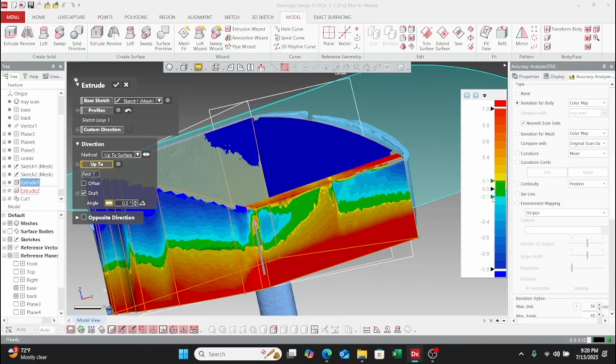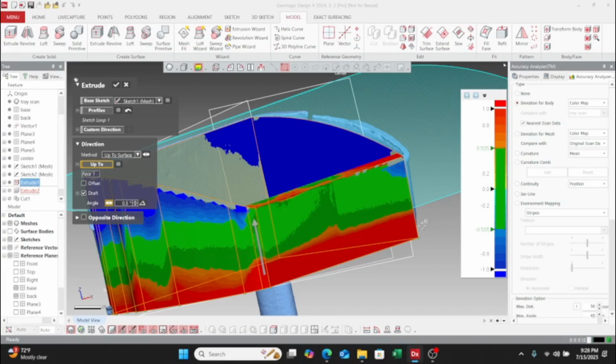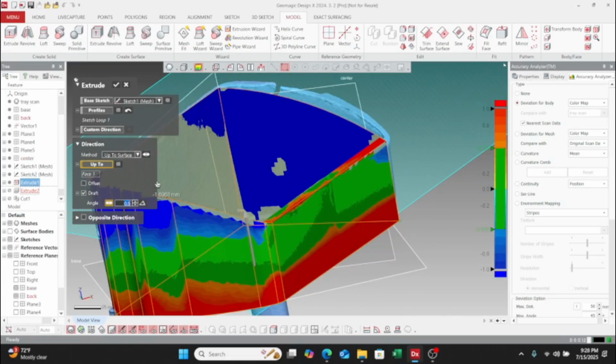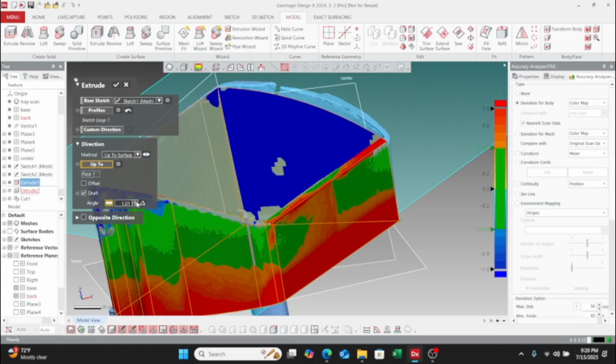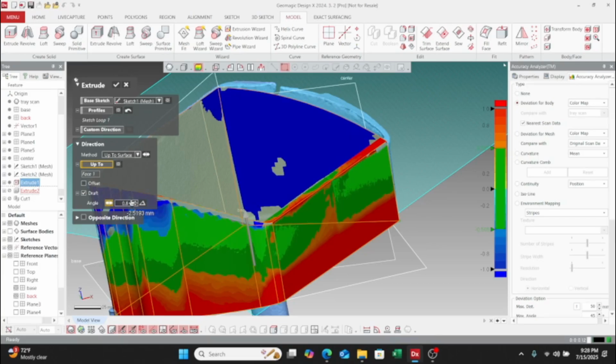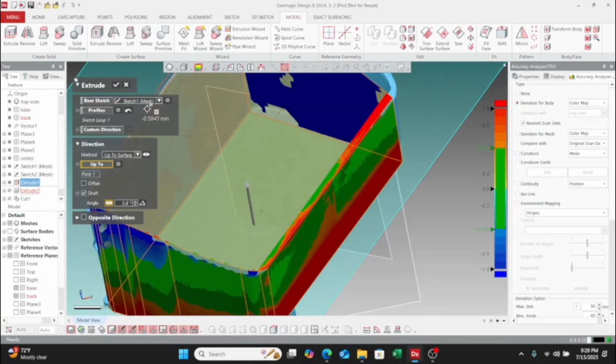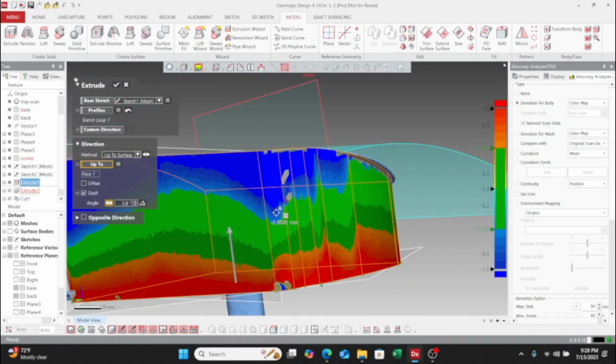So let's go ahead and make those extreme limits a little bit higher so that we have a better target for making the part green. So that makes it a little bit easier for us to have a pass-fail as we kind of toggle some of these draft angles. And so this looks to be optimal.